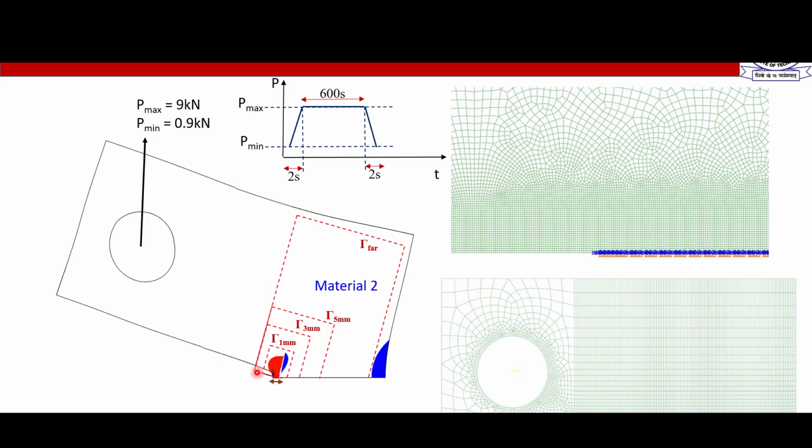So how have we done it? We have made a two-dimensional CT specimen of the same dimensions which Ramirez has used, and we can describe. We don't use the contour which comes in Abaqus by default, because if you calculate contours in Abaqus by default, Abaqus will make the first contour on one node, a single node, and then it will keep on adding a layer of nodes over and over, making contour paths.